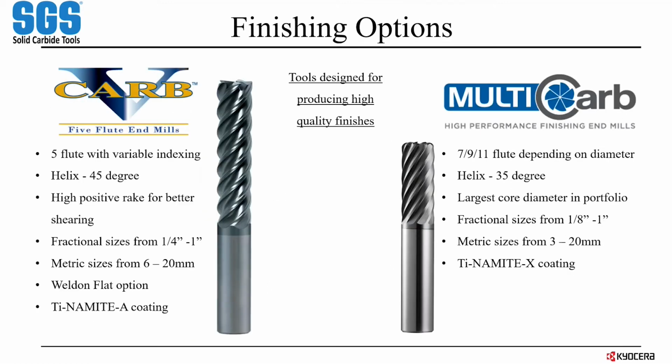So finishing, we have 2 different options that are well suited for finishing. Now, this is where people say, oh, well, I don't want to have a specific finishing tool. And you don't have to. All the tools that I previously mentioned, you can finish with those. You just have to have the right rates. And you have to know if you've been roughing with it already that your edge may not be as sharp. You may not have the shear factor there to get the best finishes out of them. So even then, you still may want to put a new tool in for finishing and then let it wear a little bit and make it a rougher or whatnot. But as far as dedicated finishing options goes, these are 2 great options.